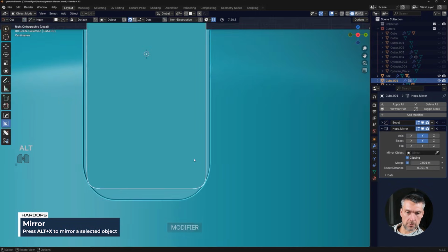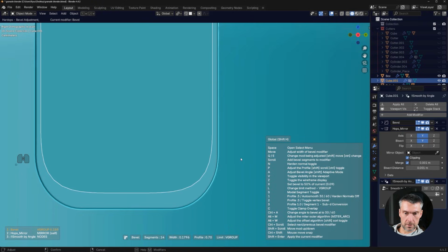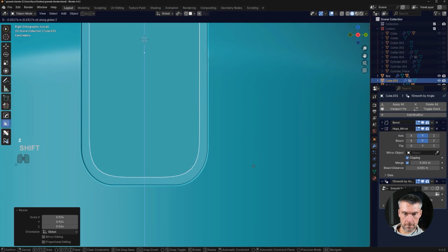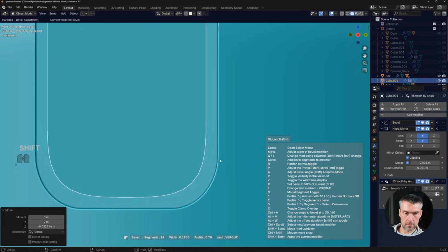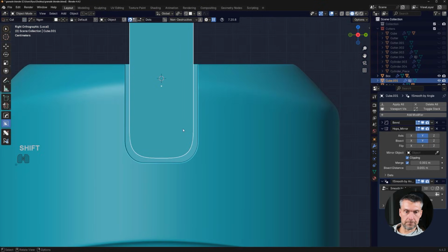So now you see the cool thing about it is that I can manipulate this bevel and I can actually adjust it to whatever I want. So if I scale this cube, right, I can readjust this bevel here, watch. See what I mean? And I need it to be more dense. So I would say like, I don't know, let's go 26, fine. Something like this more or less, okay?